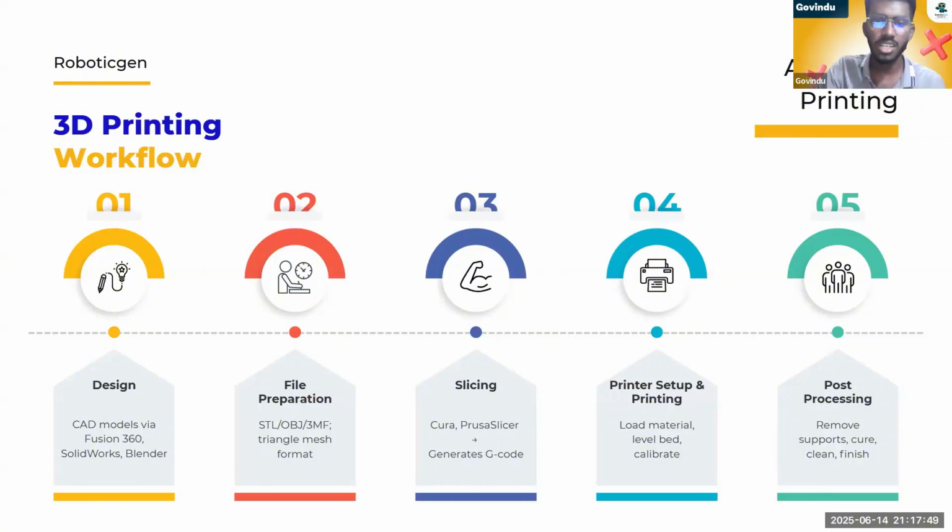After that, what you should do is the slicing part, which is done by the 3D printing software. Almost all 3D printing software does this slicing. Basically, it converts the 3D model into G-code. G-code gives instructions on where the nozzle should go when it is 3D printing. It is basically programming the nozzle, or the mechanism that prints inside the 3D printer.